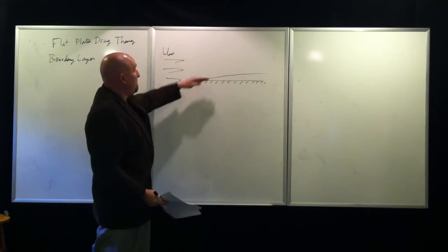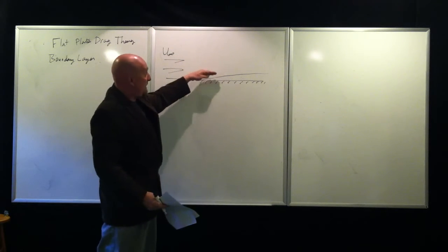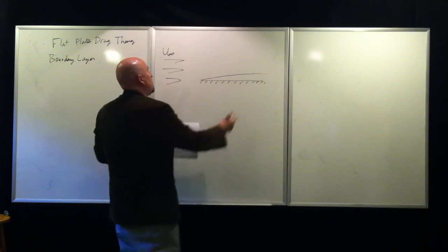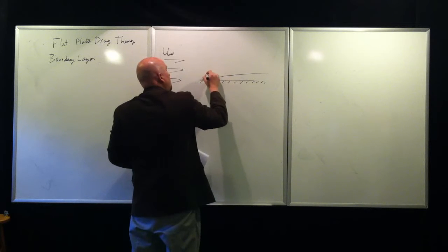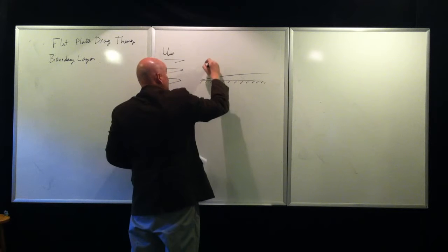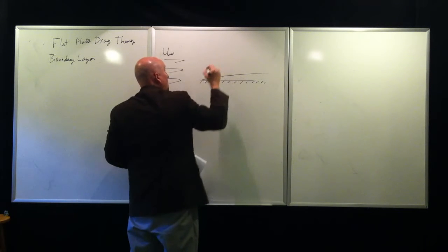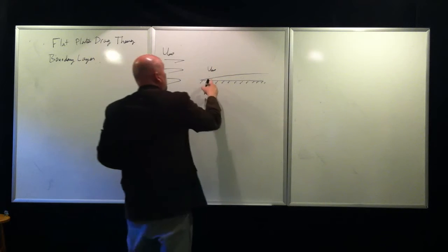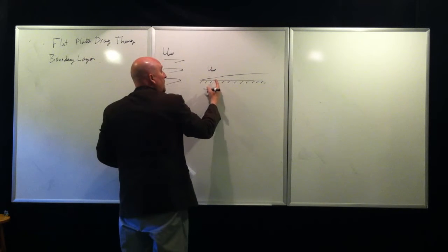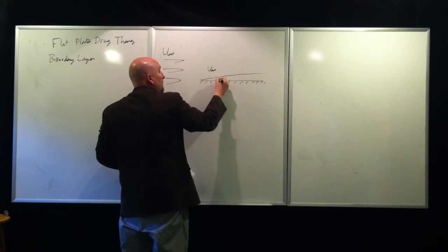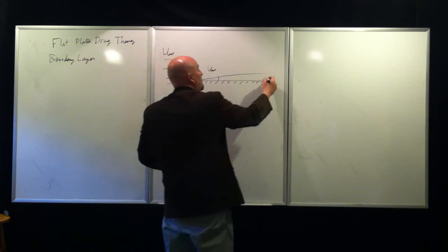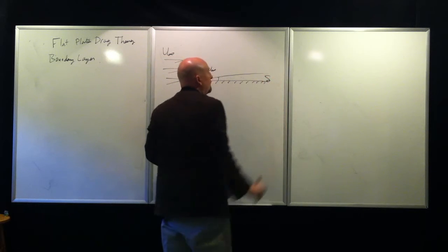Boundary layer is going to be a layer that is going to be a boundary between where you make the assumption everything out here is going to move with a free stream velocity of nearly the free stream. Everything in here is going to vary from this point up to the top of the boundary layer, and we'll represent this thickness as a boundary layer as delta.